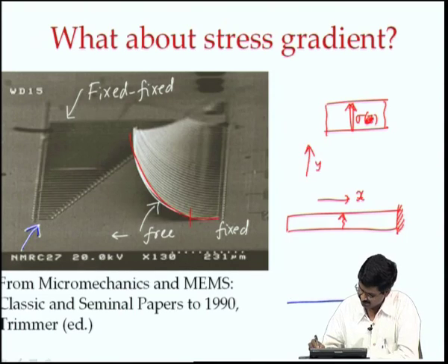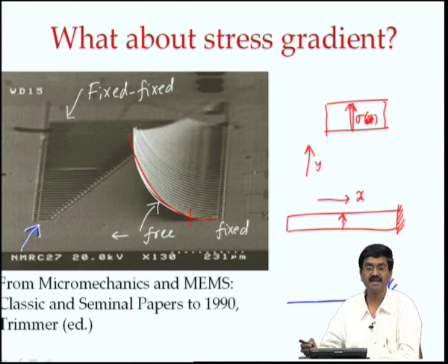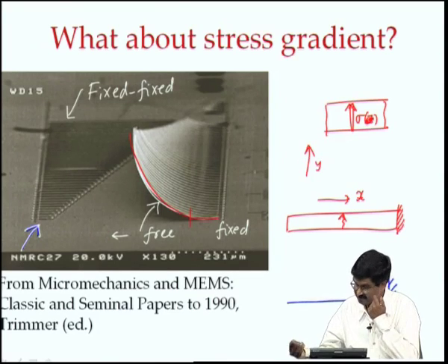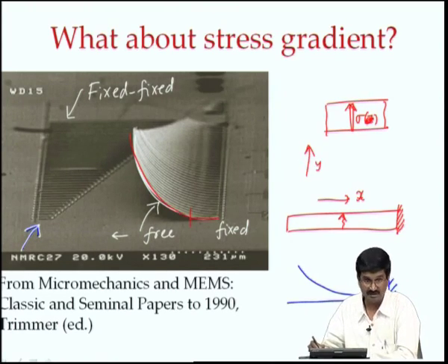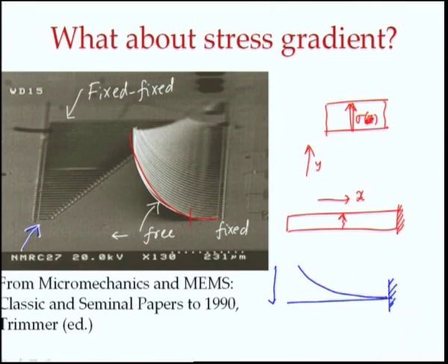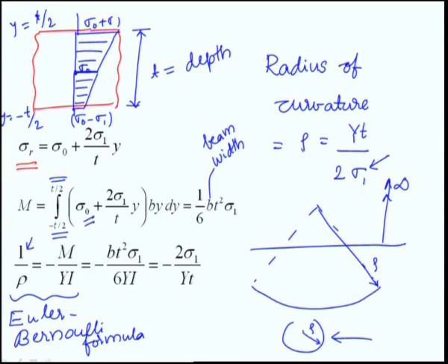Let us say I have a cantilever beam of certain length and thickness and cross section shape. If I include it there, when I see that at the end of my processing it has curled up like that, based on how much it has curled, which we can measure by measuring this height, and possibly this also may be significant, that is something like this here has become something like that, which will be a circular arc. Okay. By measuring these things you can compute what this rho is, that is the radius of curvature.